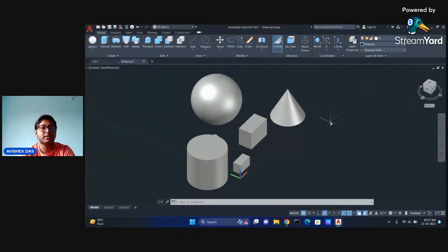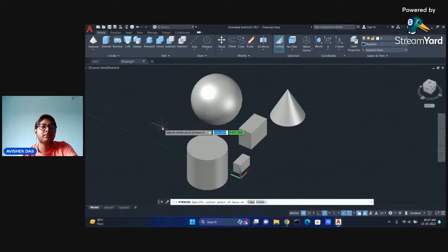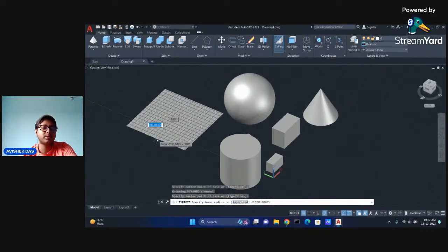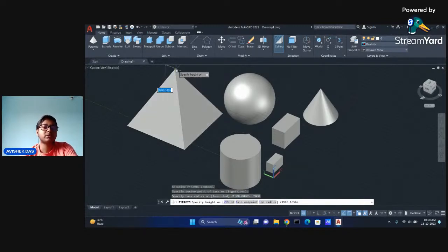After here, we can explore some more general things. What we have is pyramid. Pyramid also needs the center point of the base. Then it will ask for the side direction or the dimension of the base of the pyramid. I will give around 2000 and press enter, and now it will ask for the height.